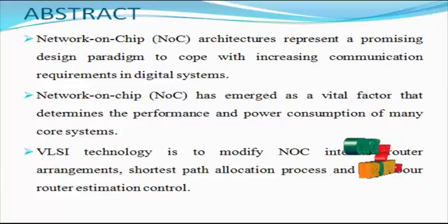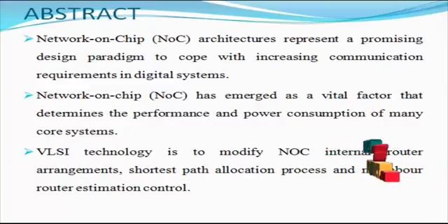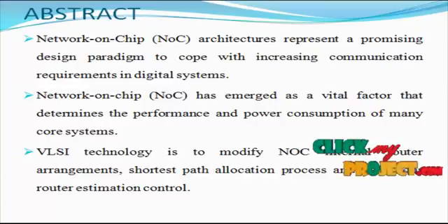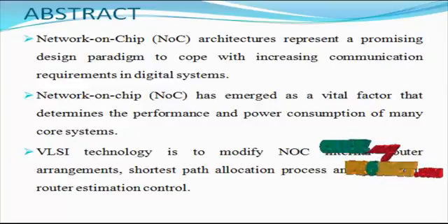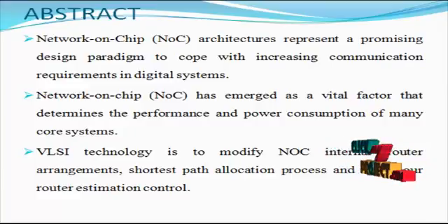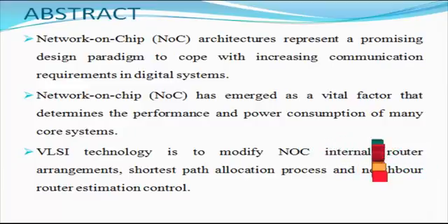The pipeline stages of a baseline packet switching router include the buffer write stage, the route computation (RC) stage, the virtual channel allocation stage, the switch allocation stage, and the switch transfer stage. On the one hand, the complex router pipeline leads to a high latency ratio. Although look-ahead routing and aggressive speculation shorten the critical path through the router, the packet switching router still occupies a higher ratio of communication latency when compared with the one-cycle link delay in a mesh-connected NoC. On the other hand, the complex router pipeline leads to a higher power ratio.